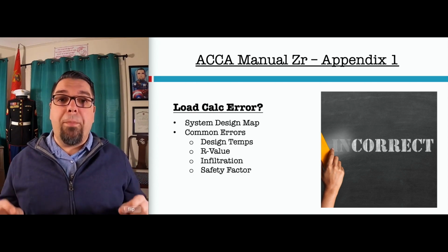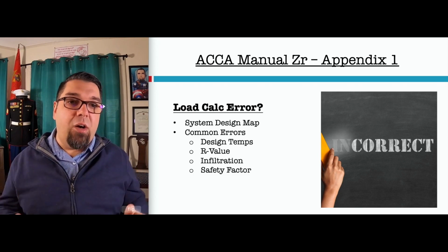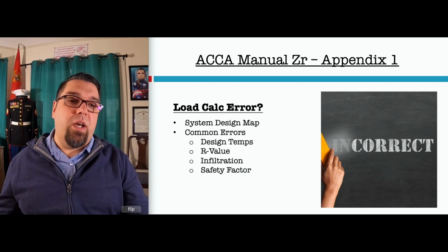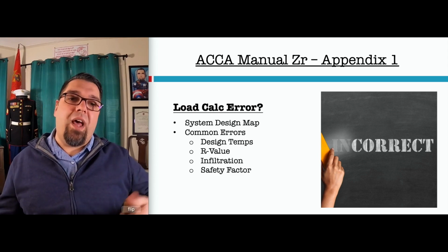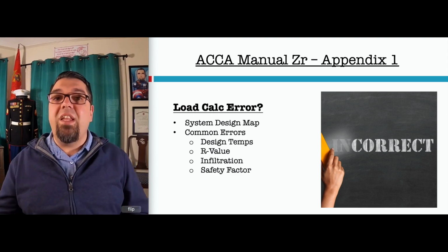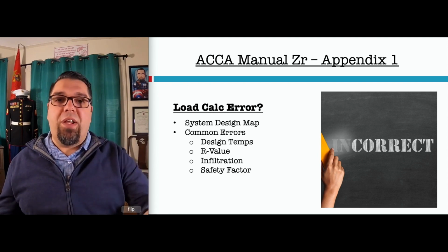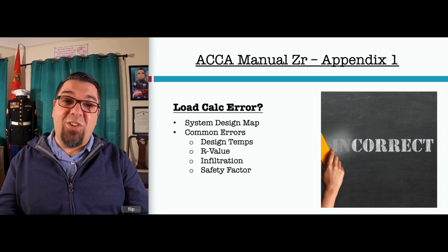So it's really important you do this work correctly to set yourself up for a house that's comfortable, and you're not trying to throw equipment and stuff at it afterwards, okay? No safety factors. You're not doing anybody a solid by making it a half a ton or a ton larger, okay? Even if it's variable speed equipment. I have explained many times in the last few years why variable speed equipment is not always the answer. You can oversize variable speed equipment too. It doesn't turn down to 1 BTU.